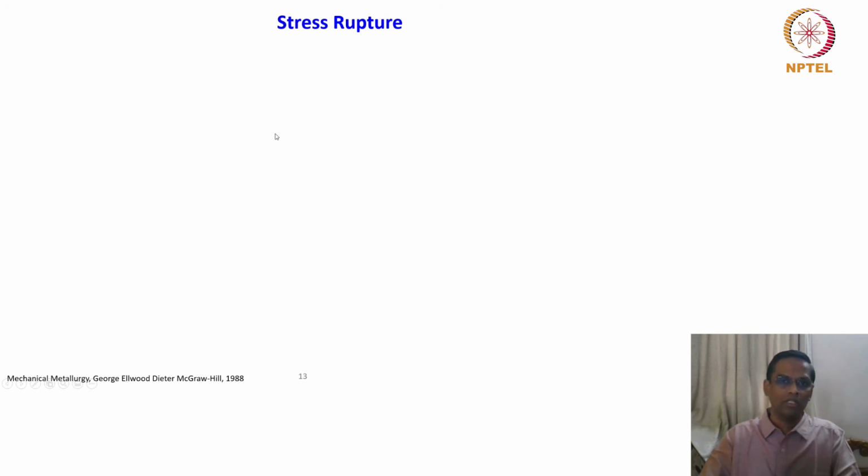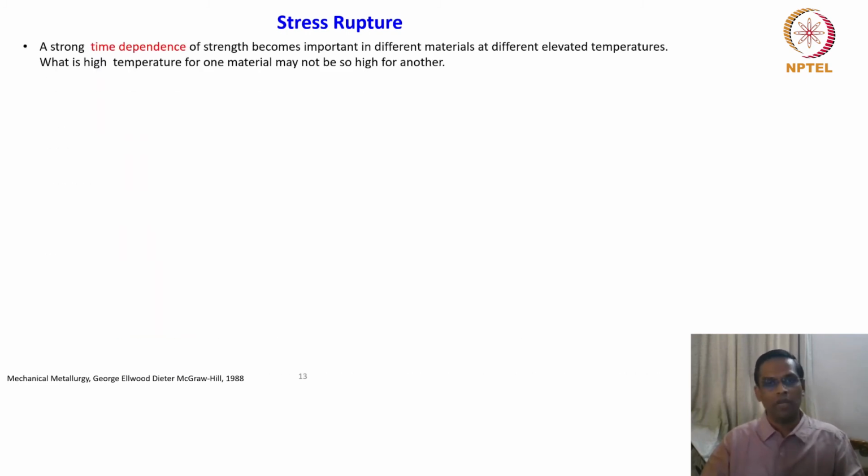Okay, there is something called stress rupture. Similar to what we discussed in creep, stress rupture is also a very important deformation behavior at high temperatures. Like time to fracture, that parameter comes only from this stress rupture test. So we are talking about the creep test and the stress rupture test. And we have already discussed why the stress rupture test is important, because there are applications where it is just a one-time use, and then the time to fracture is a very important design parameter as compared to epsilon dot 2, that is the steady state creep rate parameter.